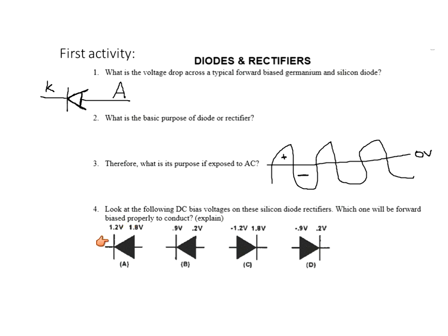Let's look at the rest. You should always look at all the answers. Well, this one has a higher voltage on the cathode, so this one is not. This is reverse bias. Okay, now look at this one right here. This is 1.2 negative. That's way below, that's below 0 right there. That's 1.8. That's not going to be good. This has a higher voltage on the cathode.